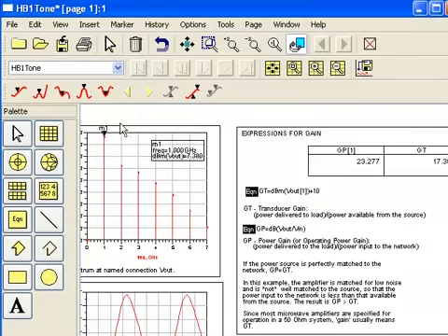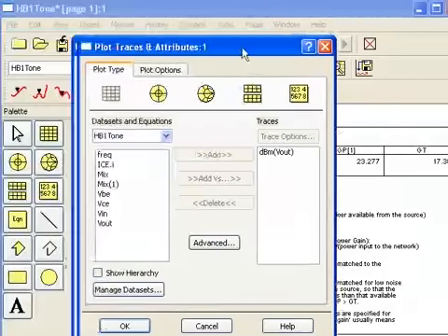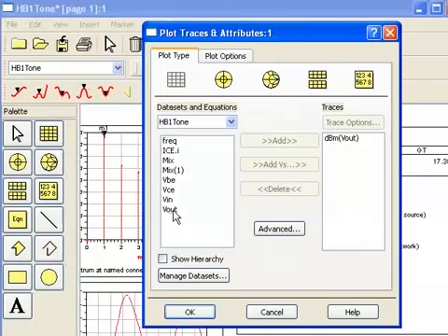Here in the data display, there's a rectangular plot that was inserted, and that contains the spectrum. For harmonic balance, when you have nodes such as V out, you simply select that node, and then you can add it, and you'll be prompted for the format. In this case, it's dBm.